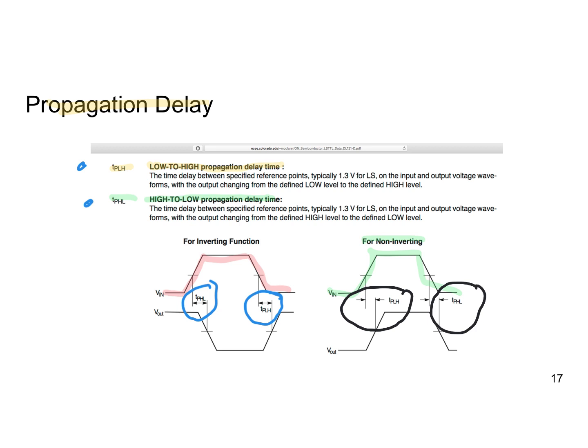Basically, it takes time. You see how this point here and this point there, if the gate were ideal, would be vertically lined up, but they're not. They're shifted in time because of the propagation delay. Likewise, that point there and that point there are not lined up. As you run pulse signals from one gate into another, the propagation delays, of course, accumulate. This is per gate. So it limits how fast you can clock or pulse a given circuit.